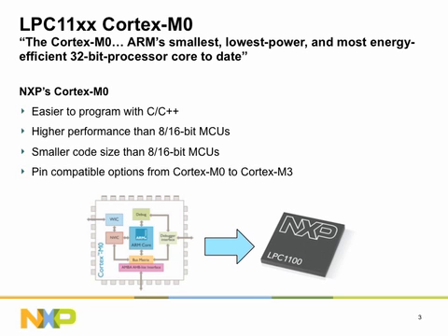The amount of memory that an MCU needs for program code can also affect the cost of a processor or the system design. The higher the memory requirement, the higher the cost. It may not seem obvious, but the 32-bit Cortex-M0-based LPC1100 offers superior code density compared to 8-bit and 16-bit architectures.